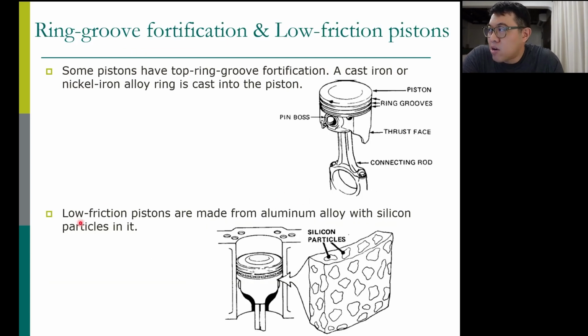Now some pistons, high performance pistons, will have top ring groove fortifications, which means that a cast iron ring is cast into the piston at this piston ring groove.